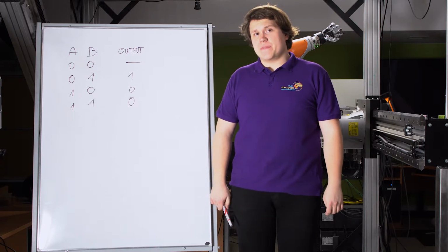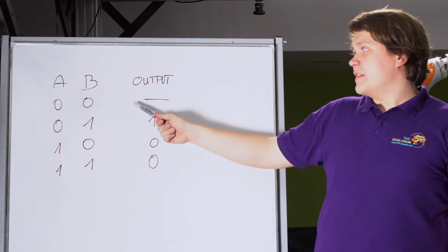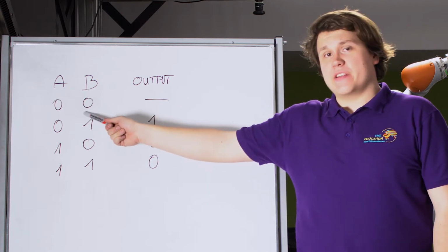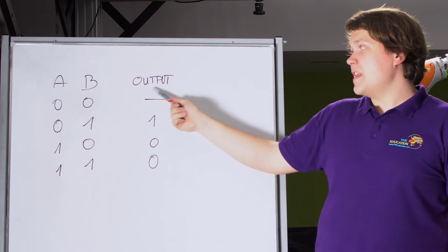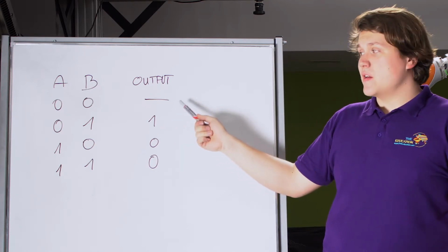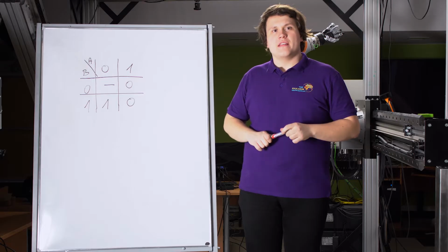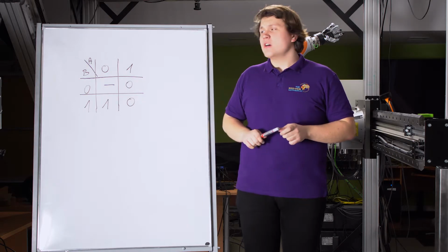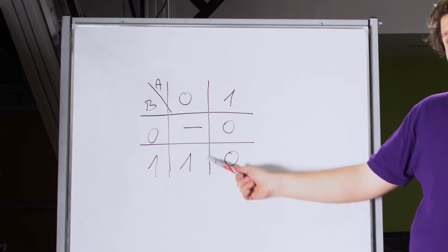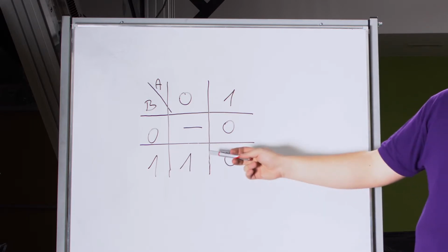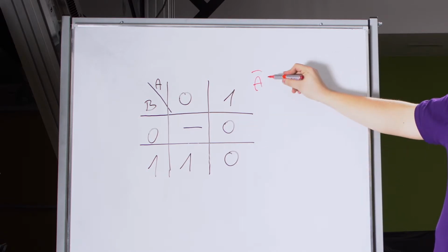Let's suppose that our logic device has only 2 inputs, A and B. But the state on the output when A and B are negative is not 0 and not 1. It means there isn't such a state in our device, so we can assume that it's 1 or 0, and it doesn't matter. Now we can draw the Karnaugh table from our function. We see that it's only one positive state in this field, so our function is negative A and B.